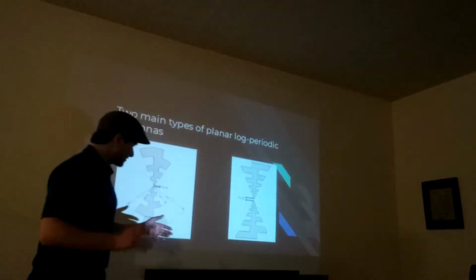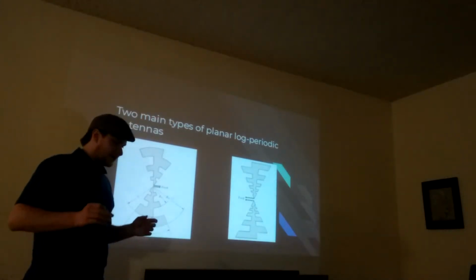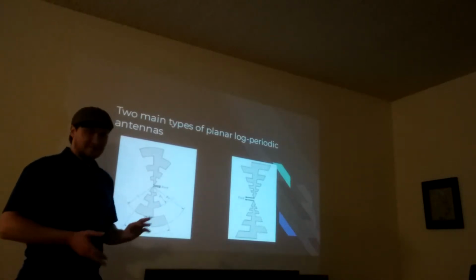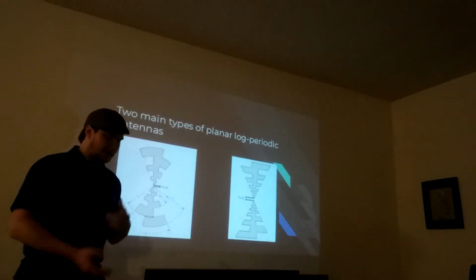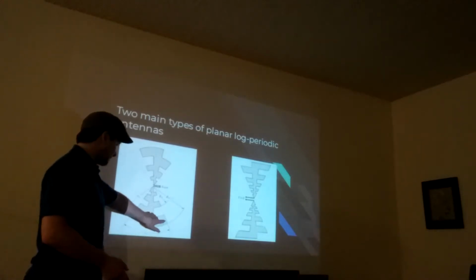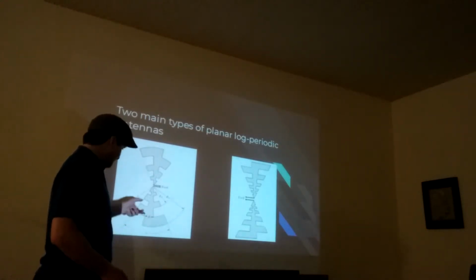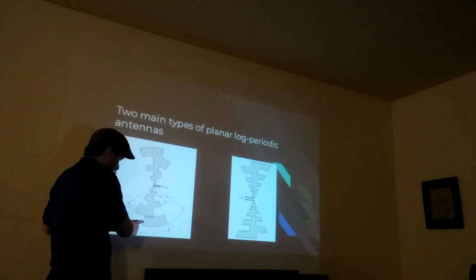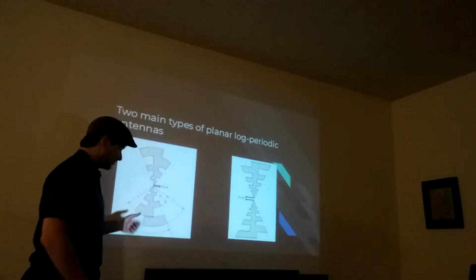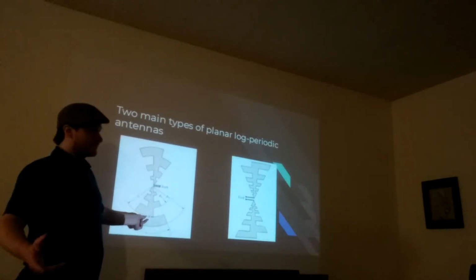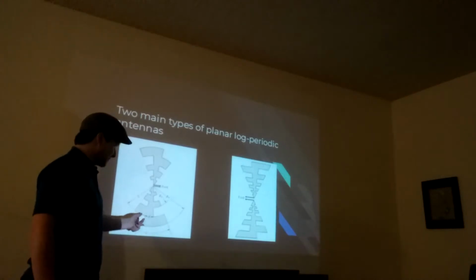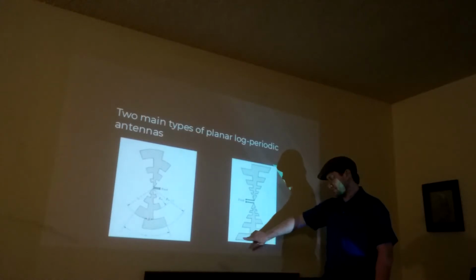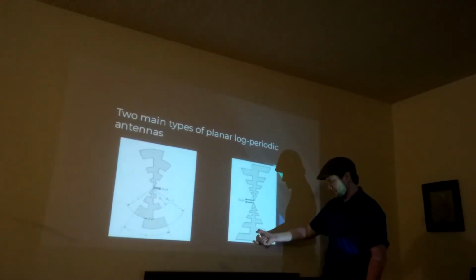The main difference is that the book, Bolaños's book, does not cover these two antennas as in depth, so I had to do a bit of digging and research to figure out kind of how they worked. And what I came across is that each of these teeth kind of acts like a patch antenna, where the length of this arc corresponds to what frequency this particular tooth operates at, similar to the middle length of this trapezoid corresponding to the frequency that this tooth operates at.